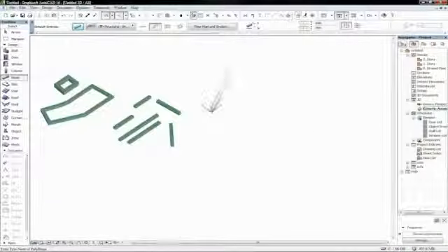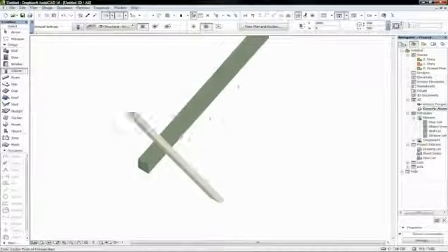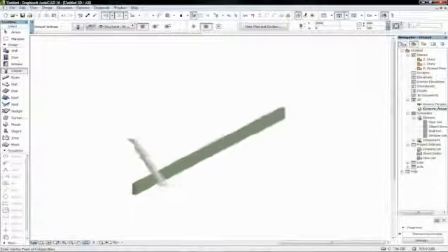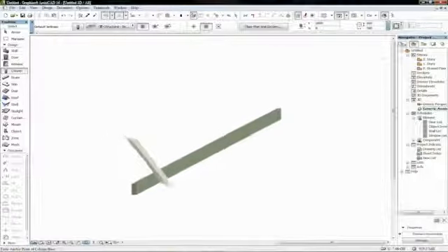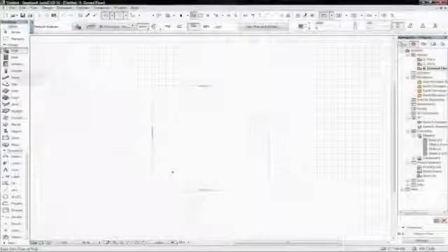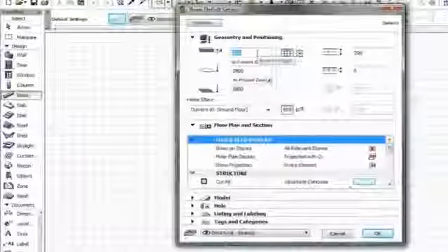Note that you are not allowed to define a 90-angle vertical beam. Although slanted beams may look similar to slanted columns, there are some significant differences between them. Beams are placed with linear geometry methods, their position cannot be vertical, and their end surfaces are always vertical. Beams made with the beam tool can have various cross sections, but the profile is always constant along the entire length of the element.